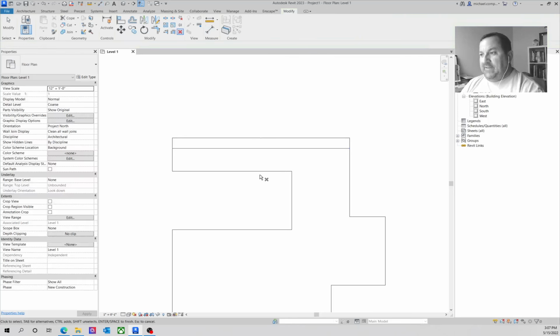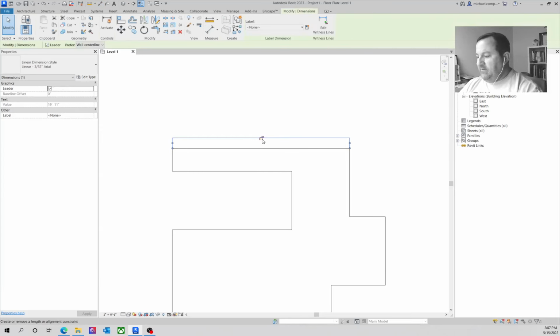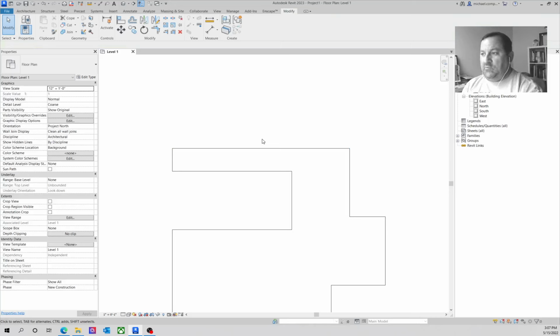So now that's if you're drawing 1:1. Okay. You guys, per your requirement, your drawing assignment was to draw at 1/4 inch scale. So even though this is 1:1, in real life, you're drawing at 1/4 inch equals a foot. So you have to divide that 19 feet 11 by 4 to get the length of space you're drawing. But since you're using an architectural scale, you just use the 1/4 inch scale. Matter of fact, let me grab one of those real quick and I'll show you what I mean.